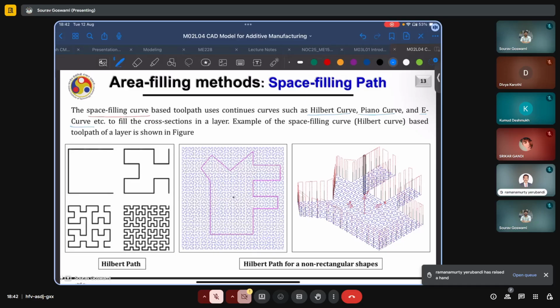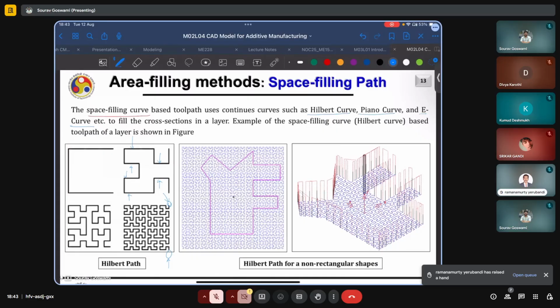Here, for a chosen shape of a given size, the offset is always uniform, as well as there is a very small number of liftoffs, and the deposition process is almost continuous. As in, you can actually start from one point, say here, and you will only lift your deposition head after reaching the other end, after depositing the entire shape, which leads to time saving.